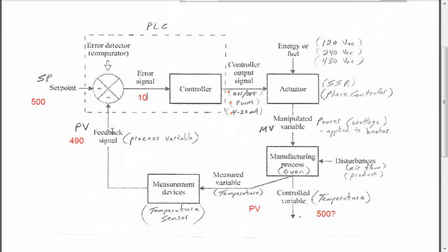Well, with the feedback loop in place, that is what we call closed loop control. In other words, you're going to ask it to be 500 degrees. And it's going to, but you're not just going to trust the machine to do that. You're going to be watching it the whole time with this feedback path. Just quickly, we could look at this heater or this oven example. We could follow it through to help you see some of these other elements in a closed loop system.